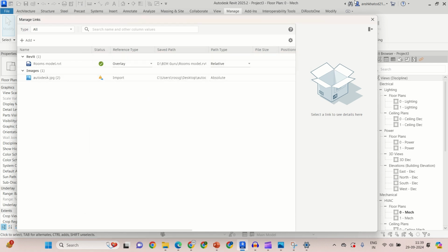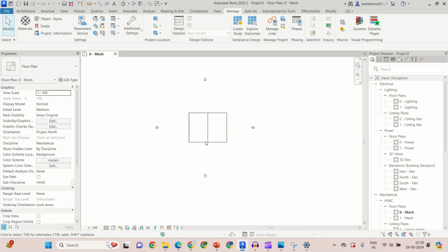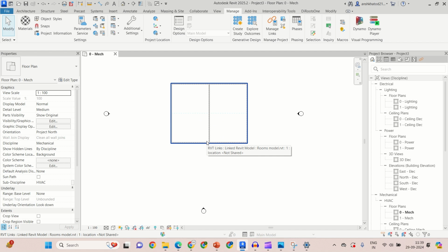If you have your architectural model in the project, you can link that one, because the spaces will be created in the MEP model. Let me give you a brief idea of how we use the spaces in the project. This will be used mainly for MEP services, and in the majority of cases for HVAC, because in HVAC we have the heat load calculation and analysis.